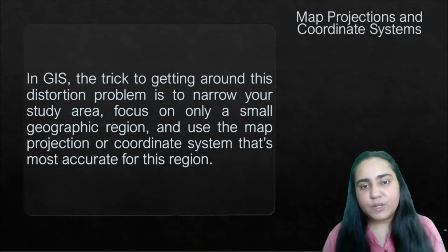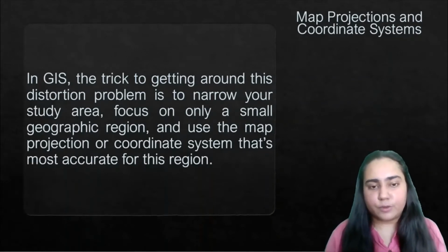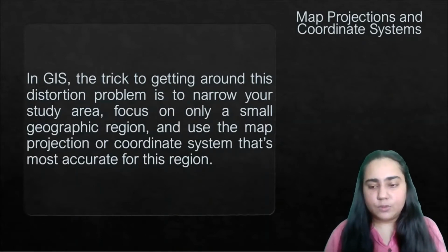And for particular regions, you will also get a particular map projection or coordinate system already available for you. So if you have a region in mind, just look for such a map projection or coordinate system which is available and then use that.